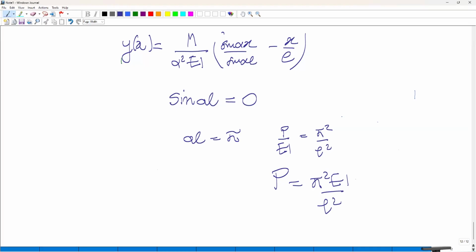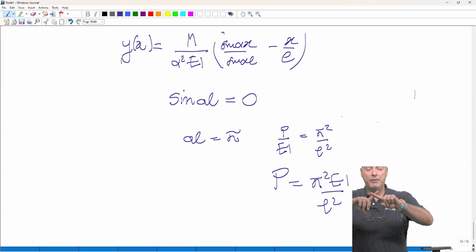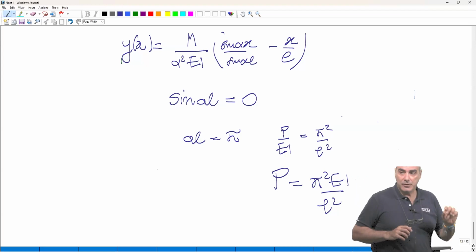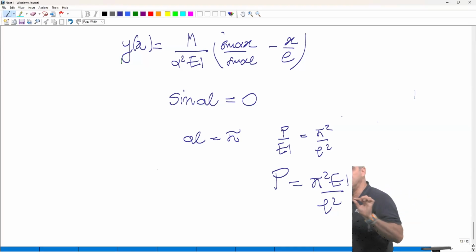So this is the importance, once more, of not only designing the connection, choosing the appropriate connections. What we have done here, we have first of all put a bracing. Bracing means, from the structural point of view, that in order to control the lateral deformation, we do not rely on the flexural stiffness of the column.